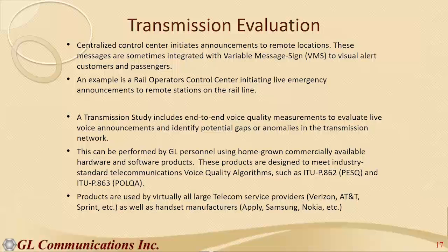So what does the transmission study include? Well, it's an end-to-end voice quality measurement. And what we do here at GL, there's multiple methods to doing this, but we find that the best method is to actually do a true end-to-end voice quality measurement using telecommunications industry standard algorithms.